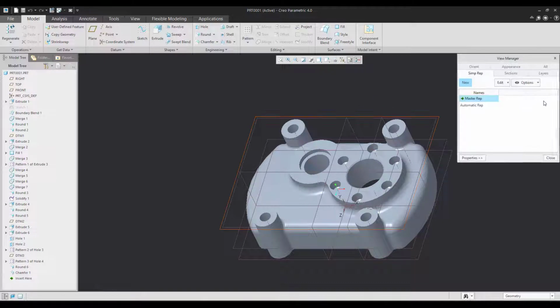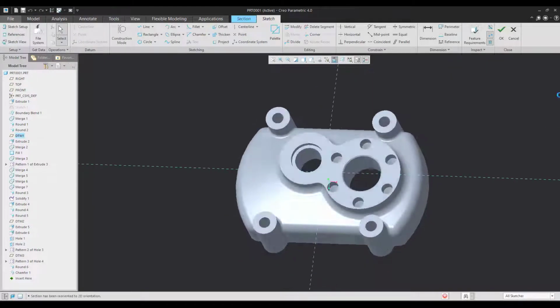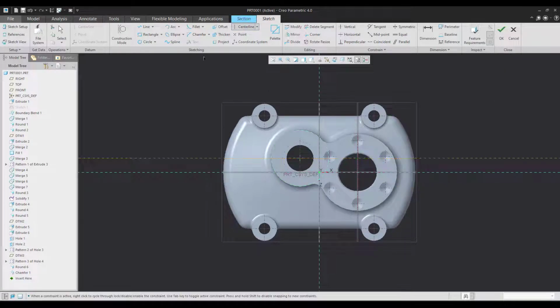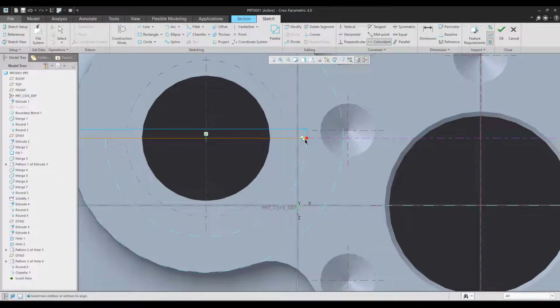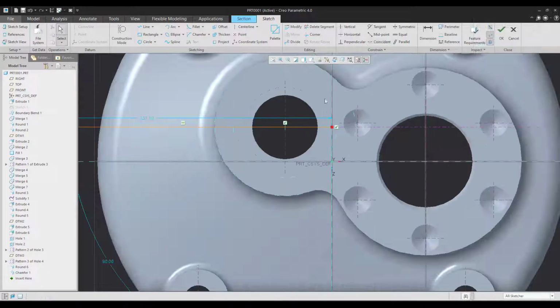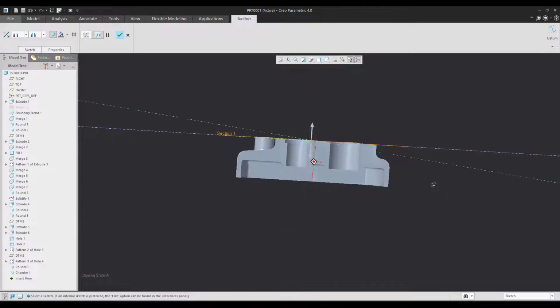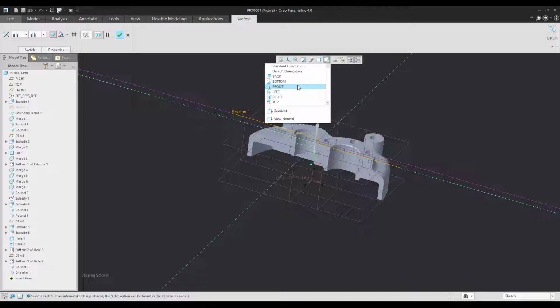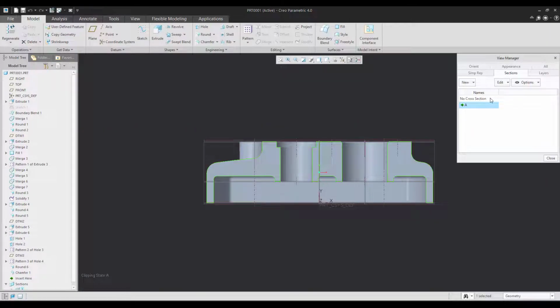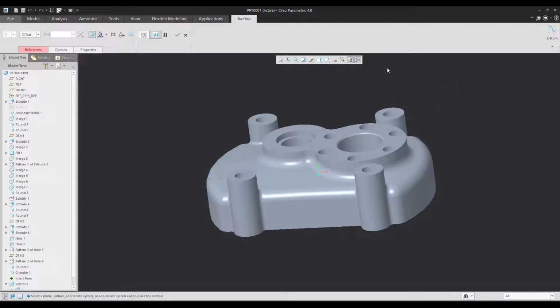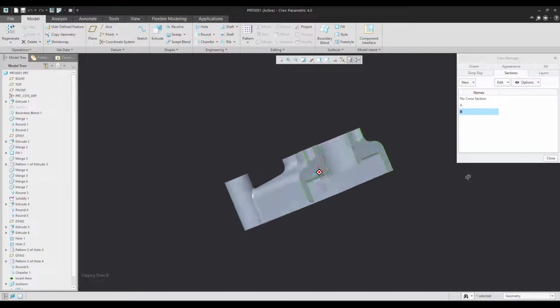Now you want to take a section view, you can start taking a section view and also check. Since I have taken the first one is A, so I'd like to show that to you. The A section cut is this way and goes this way. This is your section A. There is also section B. Section B is actually a little easy. All you have to do is select the plane which we have taken, and then it gives you section B.